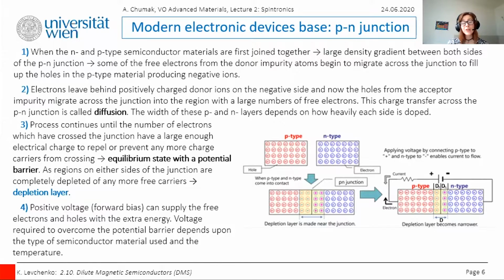One of the crucial elements of solid-state electronics is, of course, the p-n junction. The diode, the transistor, all of these key components are based on p-n junction phenomena. When p-type and n-type materials are placed in contact with each other, the junction behaves differently than either of these materials alone. Specifically, current will flow readily in one direction when it's forward biased, and it will not flow in the other when it's reverse biased, creating actually the basis of a signal diode.